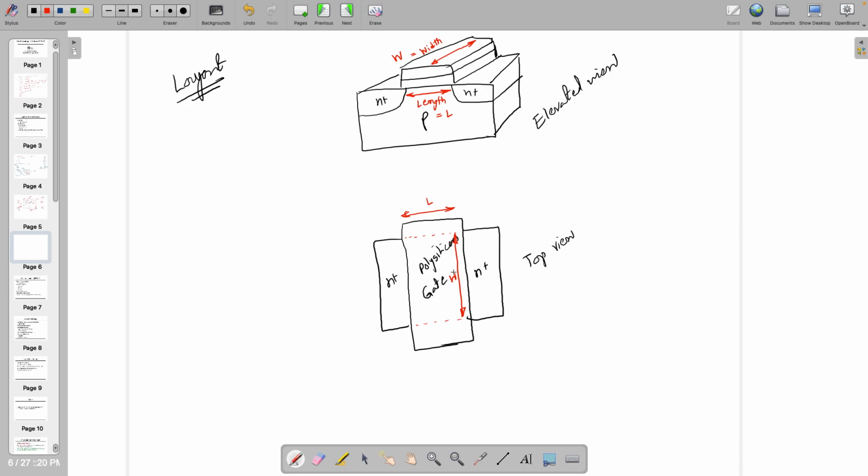So this is how the transistor looks, having gate, sorry, drain, source, any one of them, whichever you want to consider. This is source, drain, and this one is gate. And where is the body, by the way? In this particular layout which I have drawn in the top view, the white part on the board, the entire white part, is the substrate.